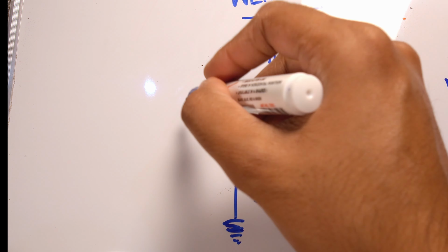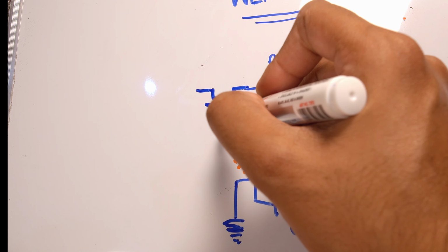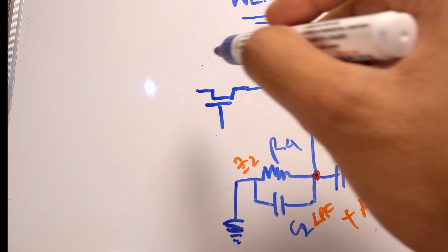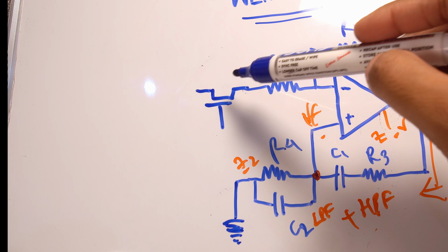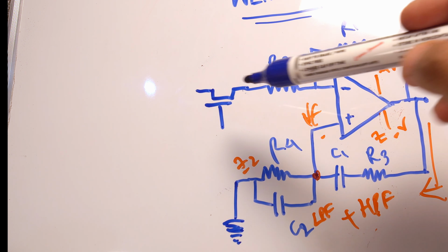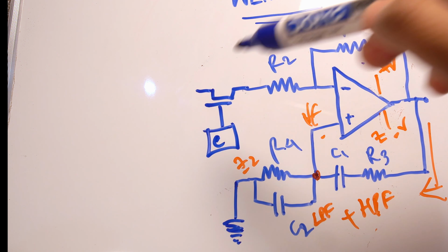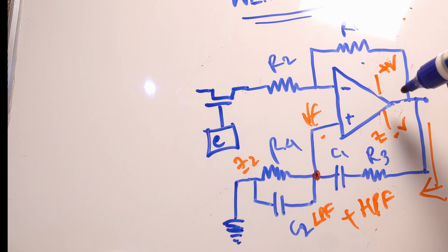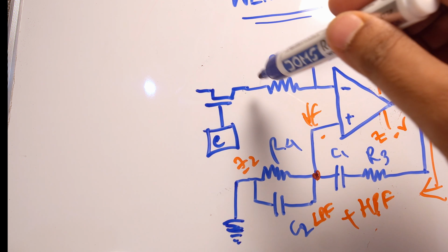And normally the best way is to have one JFET in here, and the easiest way is to have one lamp in here. So with this we can control this circuit dynamically, and there will obviously be a control circuit in here which will control it depending on the output. There will be a feedback path which will have a control circuitry which will feed this JFET.